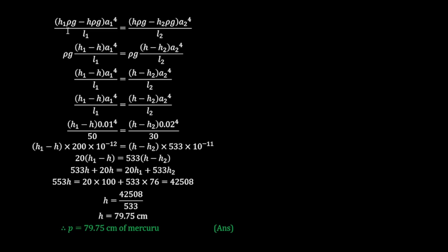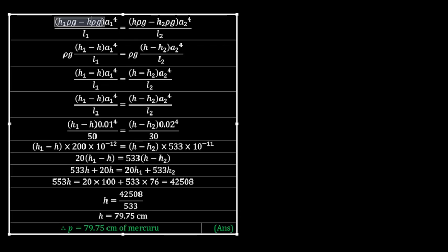So pressure P1 corresponds to a certain height of mercury, so H1 rho g. The pressure P, when expressed as a height of mercury, we write as H rho g, and this is the pressure P again. And this is pressure P2, P2 is the height H2 of mercury. Rho, the density of mercury, and g, the acceleration due to gravity, will be the same everywhere.